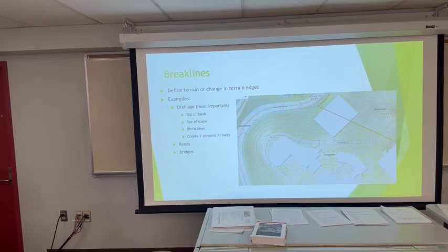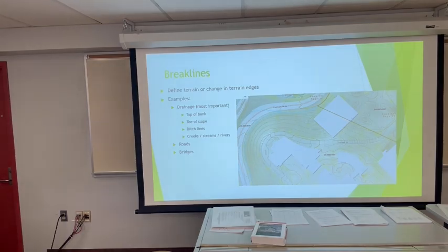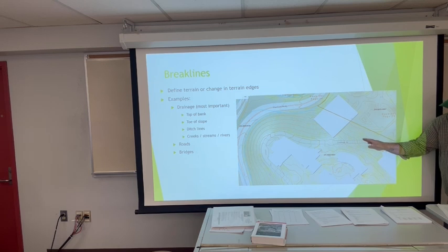What I had here is another from the GIS, with the GIS contours and part of the school here, particularly over by the ATLC and the health building and the parking garage, this portion of the roadway. See how contours are coming into the road, they change direction a touch, and then when they leave the road, they change direction again. That's a controlling feature of where a slope is changing.